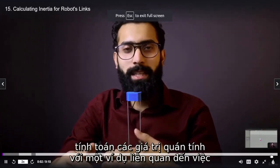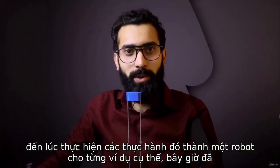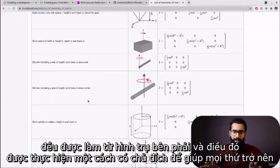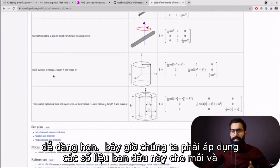an example related to the calculation of inertia values for a given example in the wiki. Now it's time to implement those practices into a robot. All of our parts for the robot were made from cylinders, and that was intentionally done to make things easy for us. Now we have to apply this inertial matrix to each and every single part of our robot.